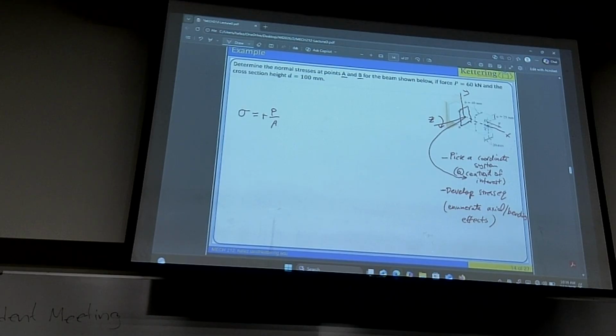All right, Ethan. Yes, when you say buckle, Jacob, it's about curling about that axis. So it curls around Z, it doesn't curl around X, it doesn't curl around Y, no bending about those two axes. So it bends about Z, then MC over I about Z should be there. We know that it could be plus or minus depending on the point. So MC over I, but M and I get the same subscript, which is Z. So we develop our equation.